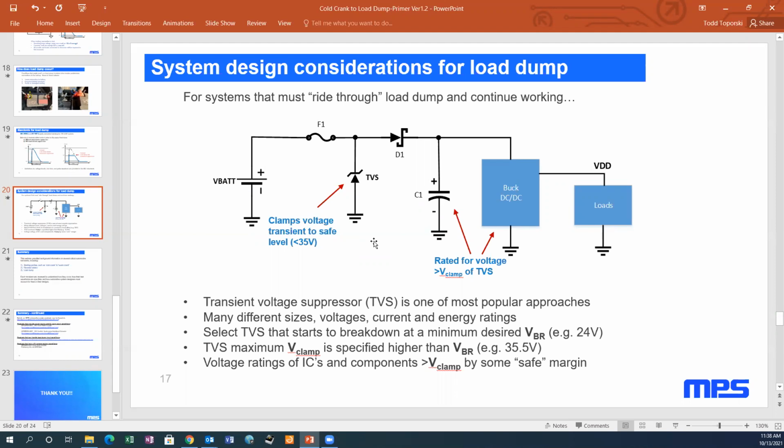And so based on that, they can then look at various suppliers of TVS diodes and try to size it correctly for the right clamping voltage that they need, the right amount of current that they think they need to shunt, and then there'll be a curve in there that shows the maximum energy that it can withstand for that period of time for the pulse duration.